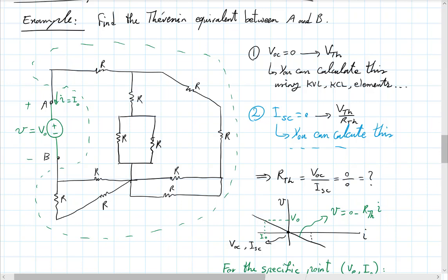So for a circuit like that, you would start by identifying where you would find a series combination or a parallel combination. You see here, for instance, down here that these two are in series because there's nothing else branching off between them. So the combination of these two, as far as the outside world is concerned, is just R plus R, 2R. And then that combination is in parallel with this other R, so you can get that combination. And then here you have these two R's in parallel, so that will give you R over 2.